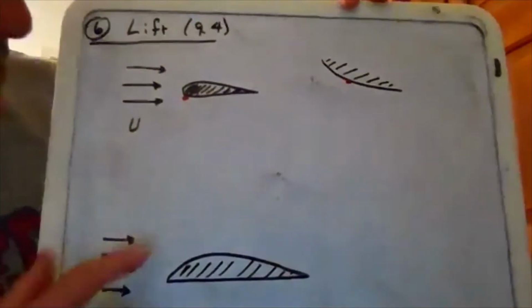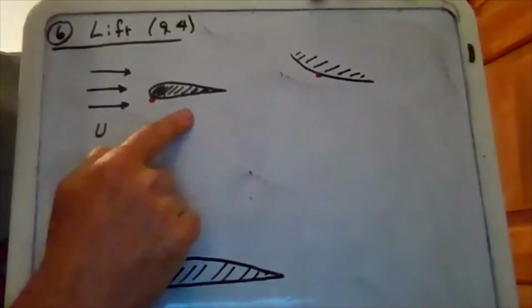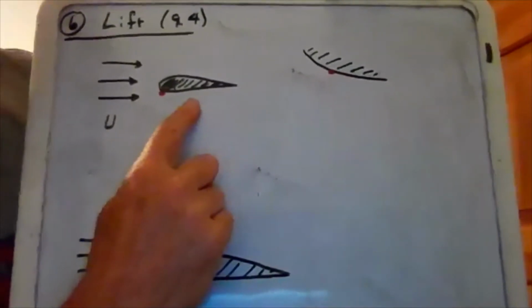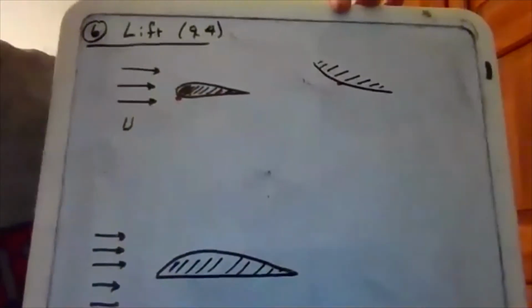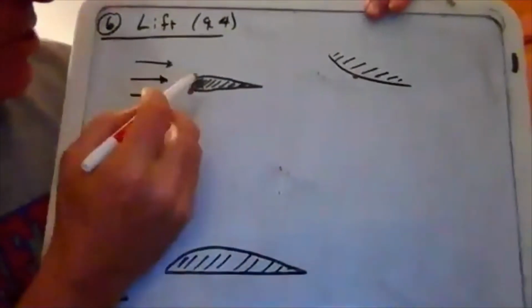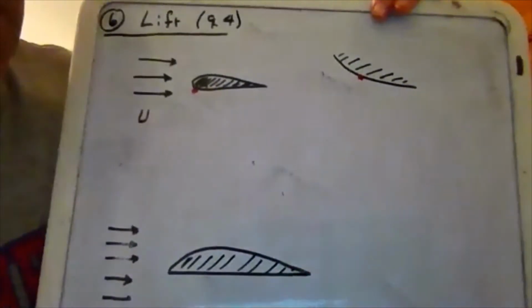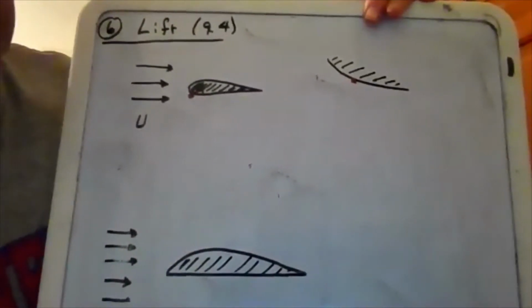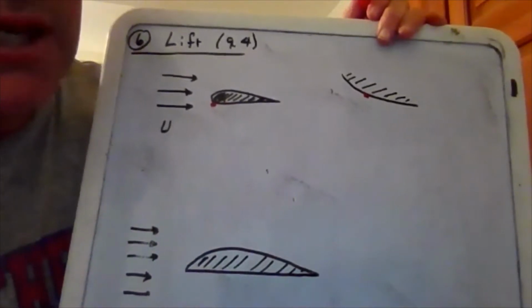But before we get going, I would also love to ask a conceptual question about it. Same idea. We're going to use U, and we're going to think about our object. This could be a section of a wing that is going to somehow be lifted up by its interaction with the fluid. We can visualize any particular situation thinking of the object as being stationary and the fluid moving relative to it. So the conceptual thing is to start by taking some point, like that point there, which I've blown up right there, and draw the shear vector at that point and the pressure vector. I think it's easier to start with the pressure vector and then get the shear vector. So go ahead and do that, 2 vectors on the same point, thinking about lift and drag.